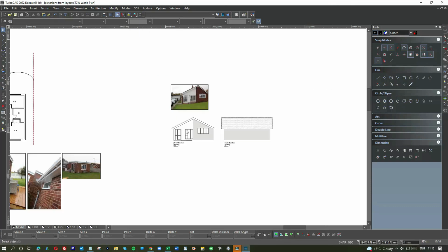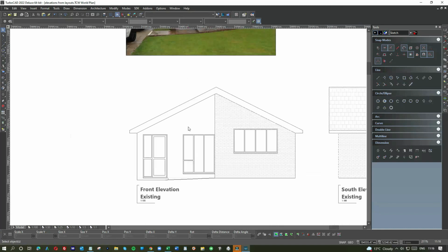Now here we have white rendering. We could leave it at that, or we could do a little cement rendering. Based on what I've done now with the fill on the brick, I'm going to let you work it out yourselves how to do a bit of rendering here. So basically it's one of the concrete fills, and you get the spacing reasonably accurate, dull it down to grey. That's what I would do, and then fill it in using the polyline tool, and fill it in sections like I've done, and it should all match up.